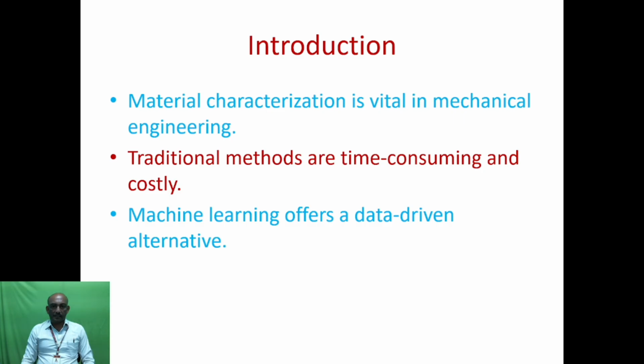First of all, material characterization is one of the predominant fields in engineering, because for the mechanical department, civil engineering department, aeronautical engineering department, for any engineering field, material characterization plays an important role, because we have to select the proper material which can stand the particular conditions of the application. For example, if we design a component or a machine to withstand low temperature applications, like in aero cryogenic temperatures, the normal material can't withstand, it will become too brittle and tear itself. So we have to design a material to withstand very low temperature, so that at low temperature it can't lose its properties.